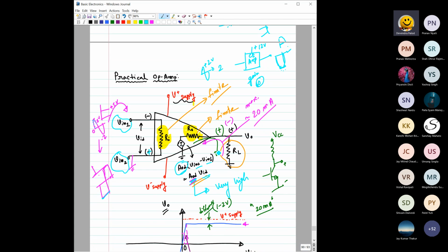But for this op-amp, if the gain is very high, say 10,000, that means immediately when you cross slightly positive, the output would immediately saturate to this value. Then as you keep moving this point, your output will keep saturating at this output. Then when you go to this one, it would be inverted, and again it will reach this, stay constant, and continue like this.